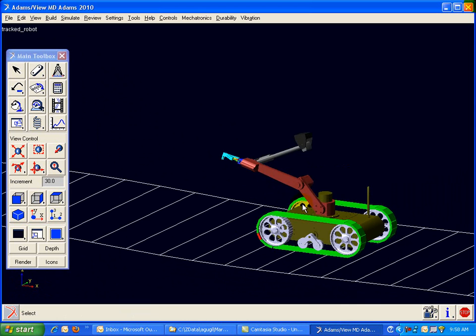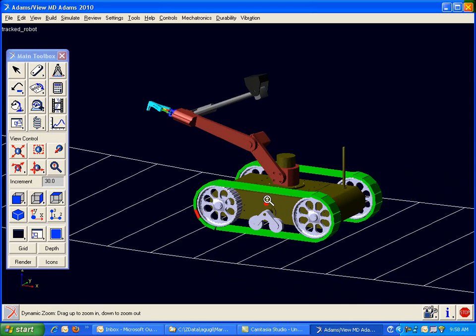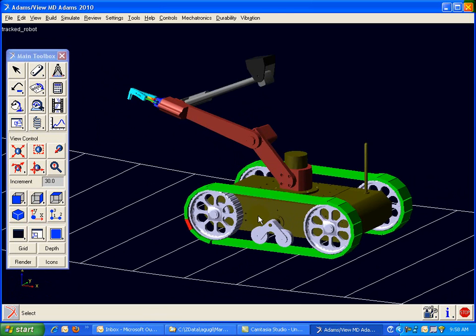And as we rotate around here, we can see a few other items. You'll notice this is a tracked robot, as I mentioned, so we've modeled the segments here with rigid track elements, but with flexible connections between them, so discrete rigid track elements with connections defining the belt properties between them. Then here we've got a pivot point around the arm and the boom, so two key pivots for moving that claw around. And so we're going to focus on those pivots today. Those are the points where we're going to control and drive with a controls model.